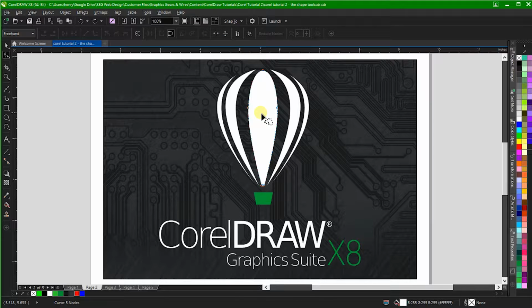You can select a node by clicking it or dragging over it. You can select multiple nodes by holding down Shift and clicking them or dragging around them. When a node is selected, you may see handles with arrows radiating from the node. These handles can be used to reshape curves.